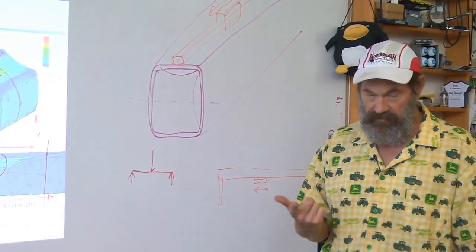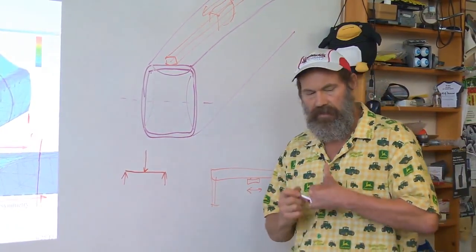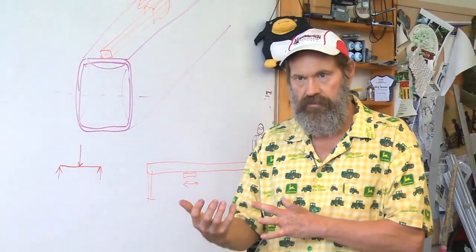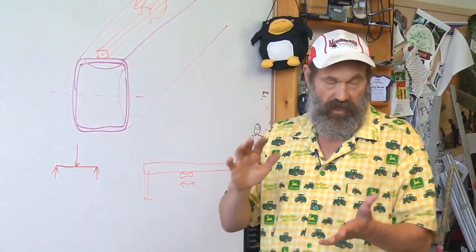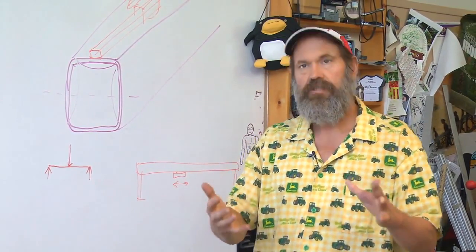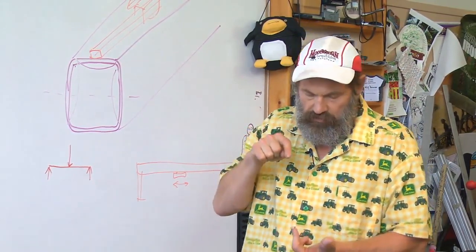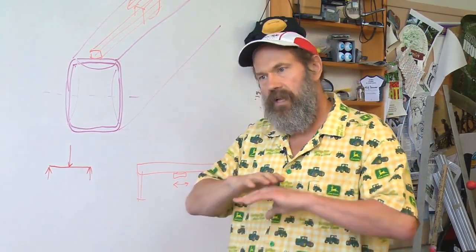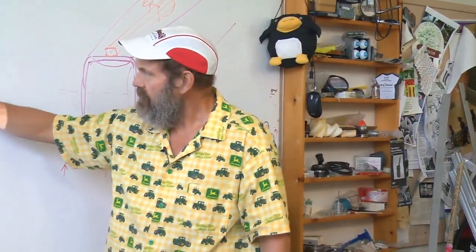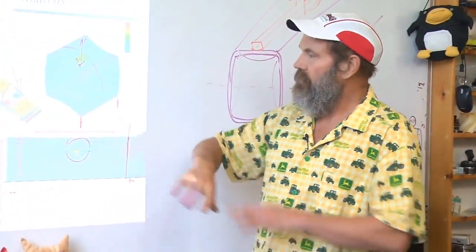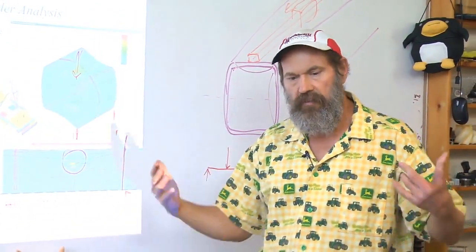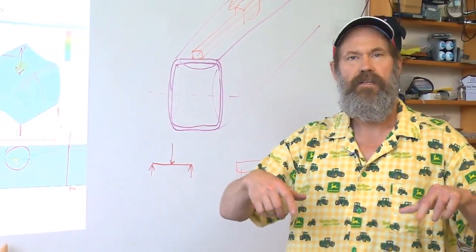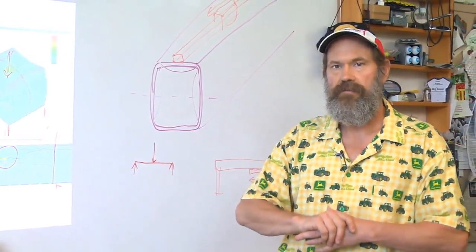So these are very, very powerful tools for your first order analysis, both for strength and for stiffness estimation, of taking the appropriate dimension slices out of a complex structure governed by St. Venant's principles, how you proportion those slices when you pull them out. To do your local quick estimate, closed form of the strength or the stiffness, it allows you then to size things in terms of your wall thicknesses, your dimensions, complete the rest of the design of the structure, and then when you have the rest of the design structure, then you can do the finite element analysis on the complete machine to check the strength and stiffness of it.